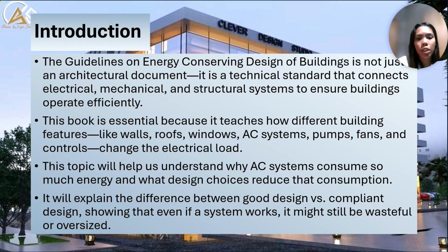It will explain the difference between good design versus compliant design, showing that even if a system works, it might still be wasteful or oversized. Electrical engineers must know how motors, fans, chillers, and HVAC controls affect total energy use and monthly electricity bills. Oversizing equipment means higher current, bigger breakers, larger cables, higher demand charges, and unnecessary operating costs.